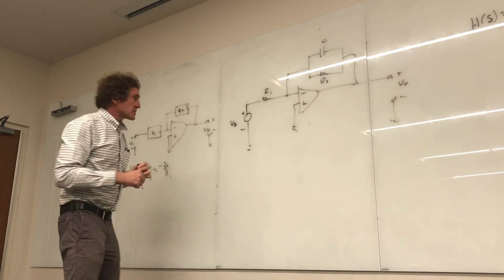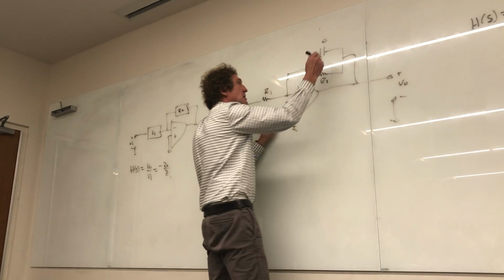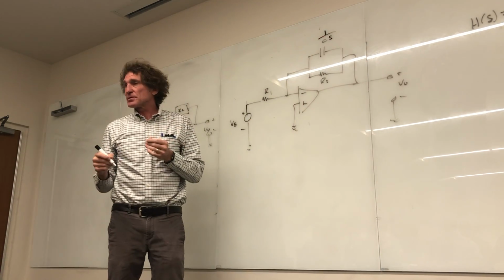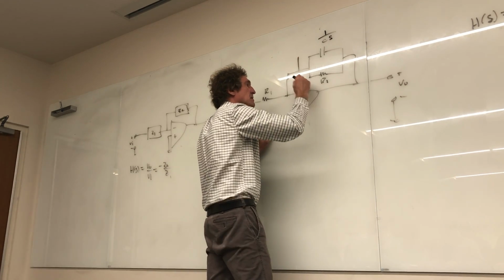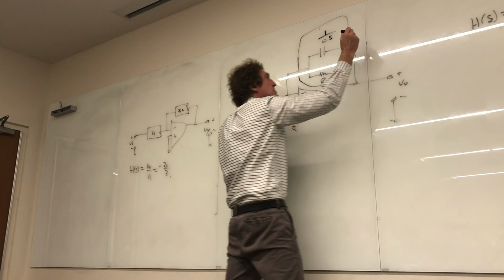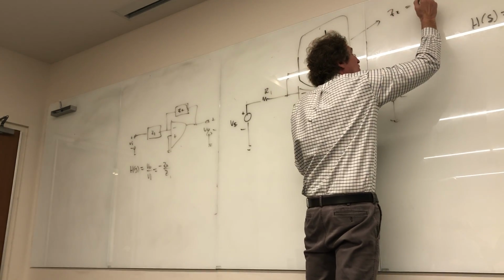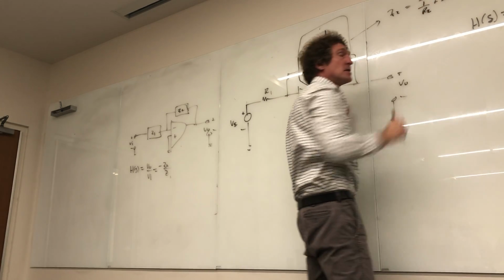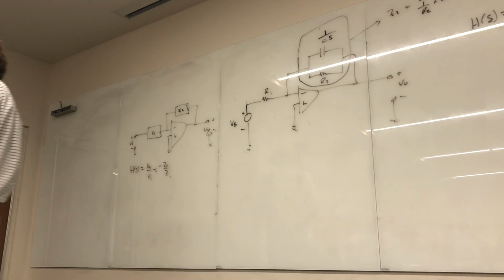So if I want this, the first thing I have to do is put the impedances in terms of the S domain. Here, the capacitor has an impedance of 1 over CS. The resistor is just R2, do you agree? Now, this entire thing I'm going to label just Z2 so you can see it. Z2 will be 1 over 1 over R2 plus SC, agreed? That's 1 over 1 over the first impedance plus 1 over the second impedance.